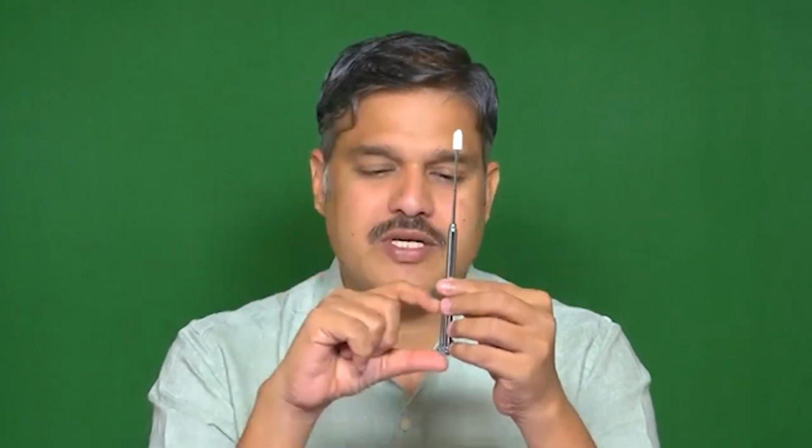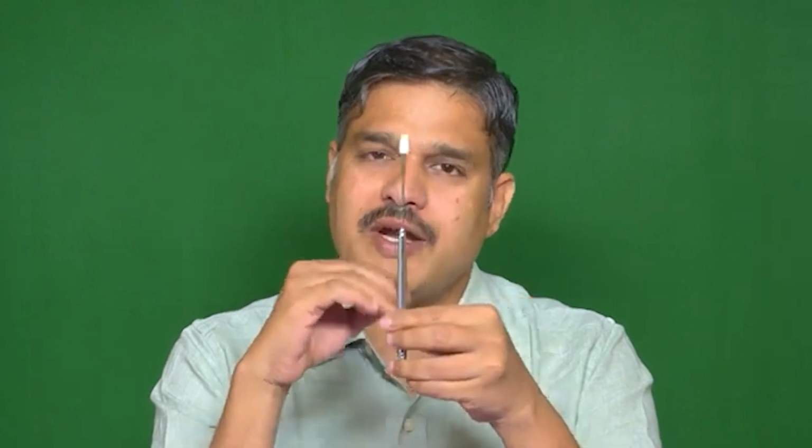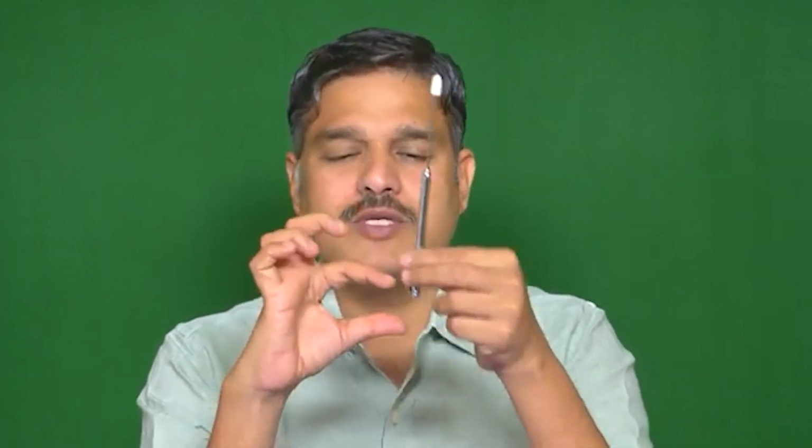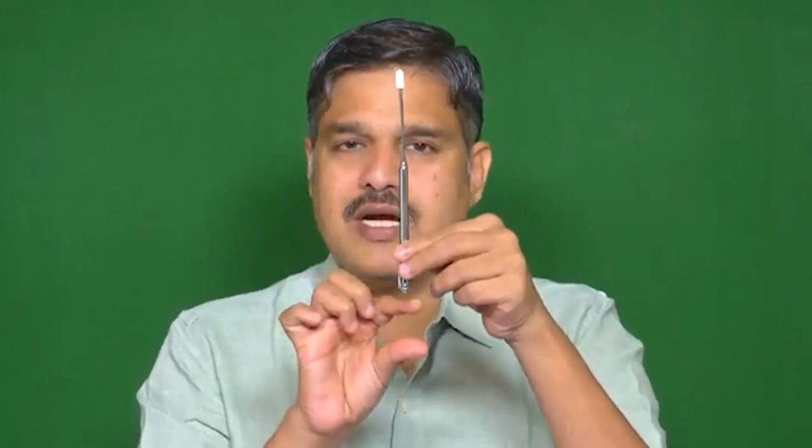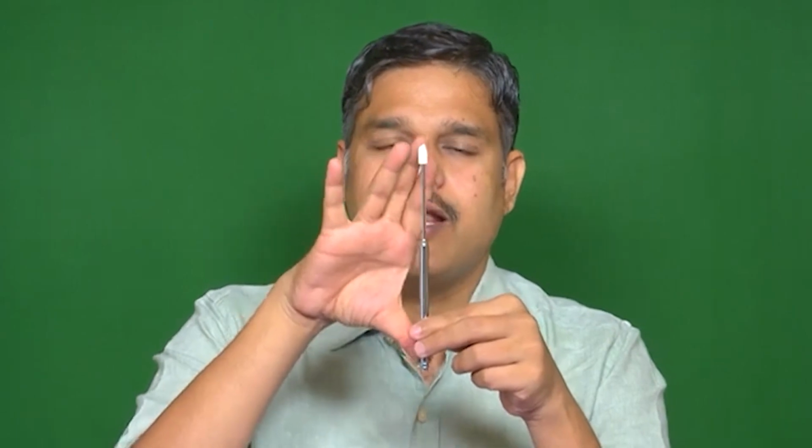This base isolation technique will not allow the vibration energy to enter inside the building. That means we are isolating the building. So ground is here, building is here, and in between we place some material such that the frequencies which are relevant to the structure's vibration will be filtered out, and other frequencies will enter which will anyway not cause harm to the structure. So that is the concept of base isolation technique.